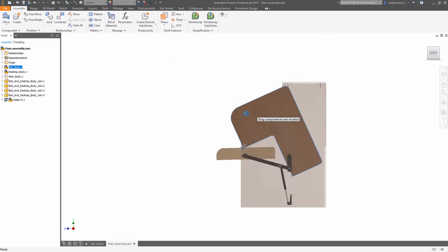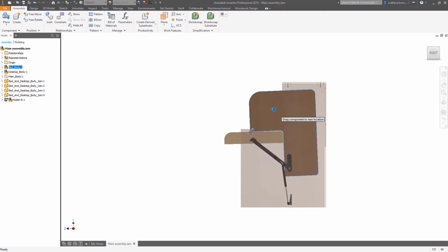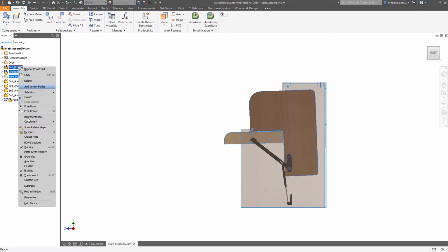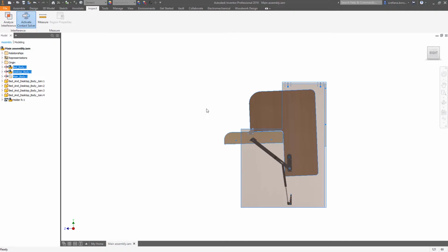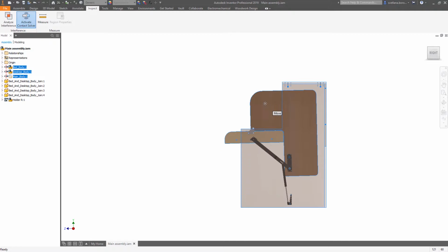So we can see from the side how this mechanism moves. And if some adjustments are needed, you can easily do this by just changing the skeleton parameters. Okay, we can use a contact solver to check collision and see where this item actually stops.